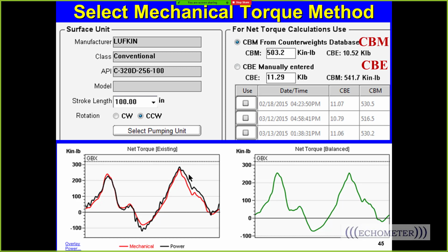So we're just doing the counterbalance moment from the weight of the crank and the weight of the weights, and then the wrist pin is attached to the pumping unit, and that's all handled by structural imbalance. So the wrist pin weight doesn't matter. It's somewhere else. Just the crank and counterweights. That's correct.